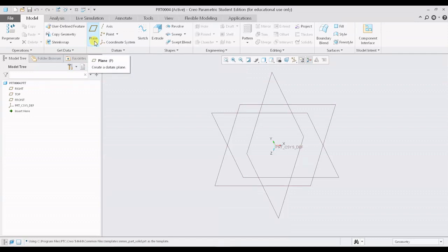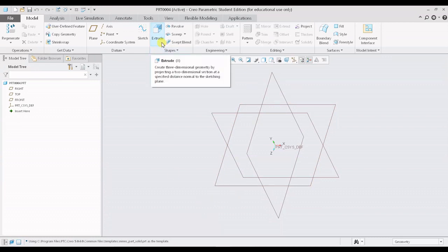So now I have opened the part module and let us try to work on the creation of the aircraft wing. For that I have two options. First, I can create a sketch on this particular front plane. I will be having the aerofoil ready with me. Then I can click on the sketch and extrude it. The second option is I have to click on extrude and select the plane where I would like to extrude my sketch, and there I have to import the aerofoils. So I will be going with the second option.